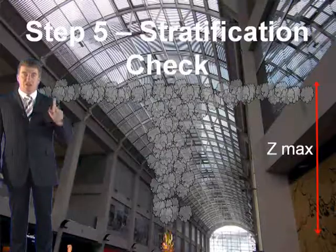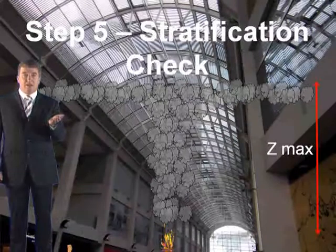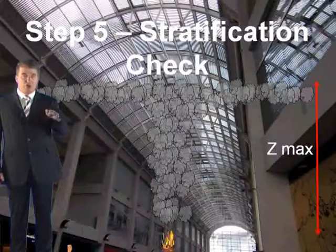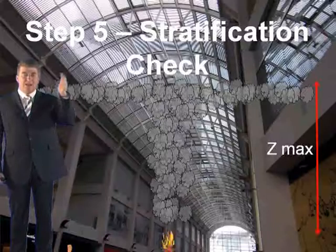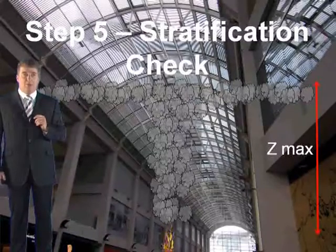So now you know how much smoke we've got and how hot it is. We now need to start determining how you're going to extract that from that building. Before we do this, you just have to at least consider the phenomenon called stratification. Now, in tall buildings, this is significant. In this building, it's only got a clear layer height of 10.1 metres. You're not going to get stratification in this building. You're generally looking at about 20 odd metres. Anything under that, you're not going to look at. So stratification in this case is not a problem.